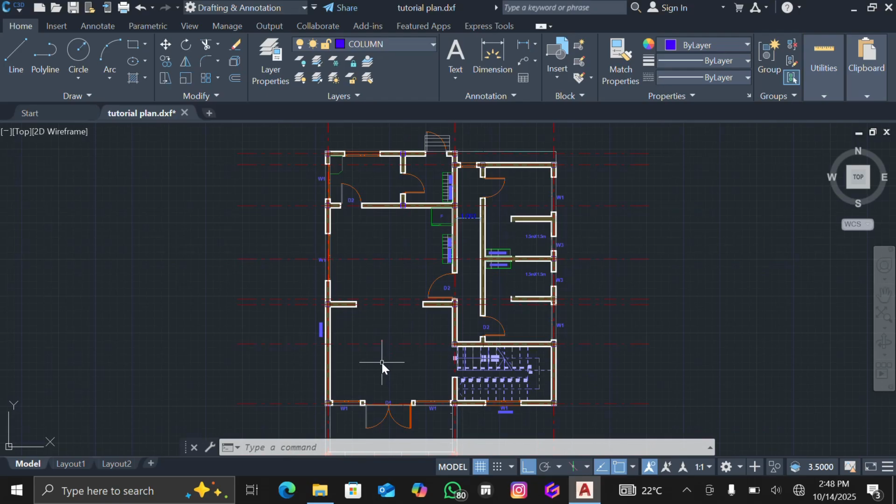As you also know, we have principles to follow when we are coming up with our panels. Don't make a panel which is far beyond 30 square meters. Take an example, if from this column to this column is about 7 meters, and also from here up to here it is about 7 meters, that implies that you have something like 49 square meters. That is already totally wrong. That's why I was telling you that it shouldn't go beyond 6. You get it? Shouldn't go beyond 6.